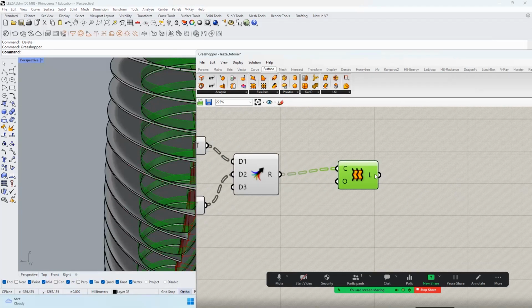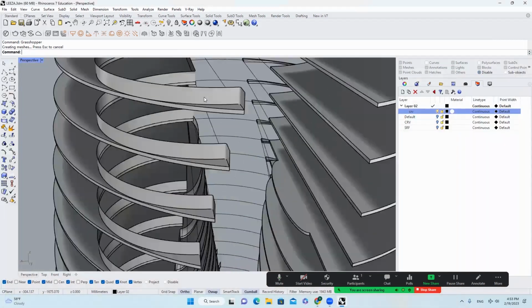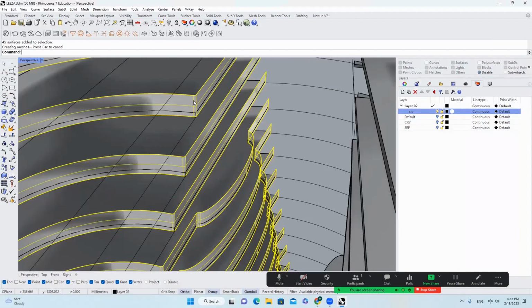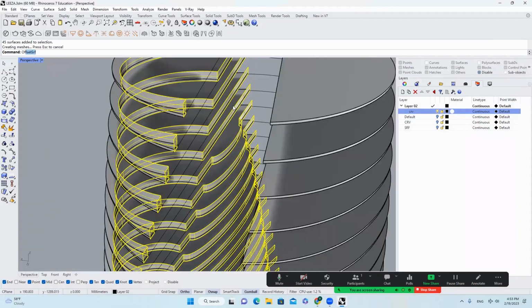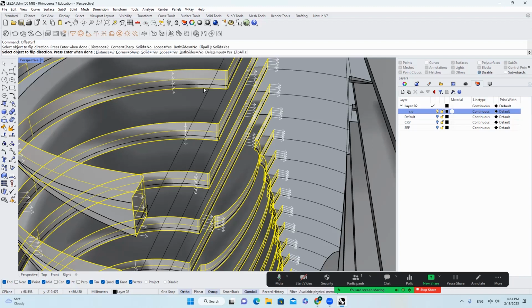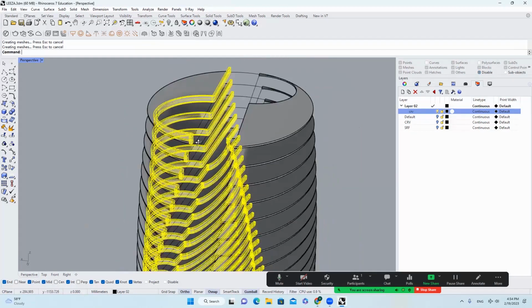I'll hit all those surfaces one more time, and then I'll offset to the other side. So I'll just have an offset surface. This time I'll offset everything for 2 feet, and then solid to yes, loose to yes, hit OK. And I got it, something like this.